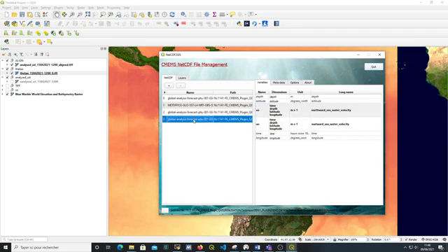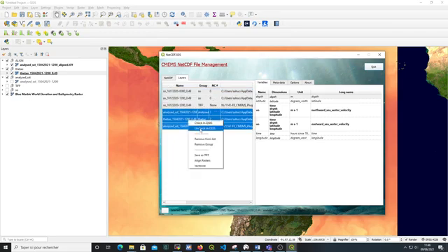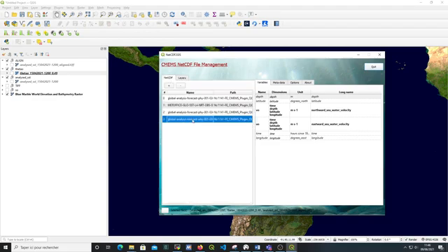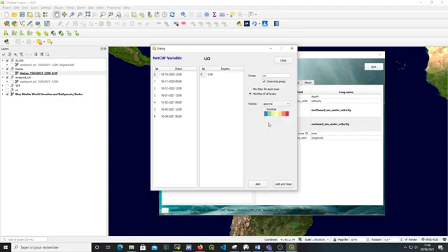Before drawing this vector field, we are going to hide the two layers we have aligned before. So you can select the three last layers and click on Uncheck in QGIS to hide these layers. Here, if we go back to the NetCDF file containing U0 and V0, we are going to import and add each layer to the QGIS project.